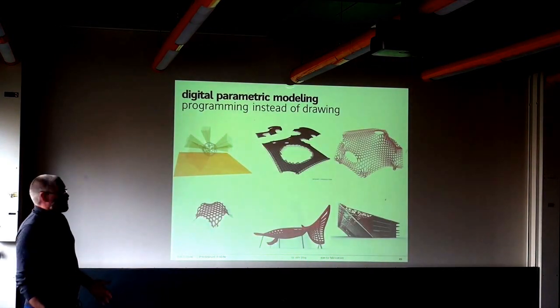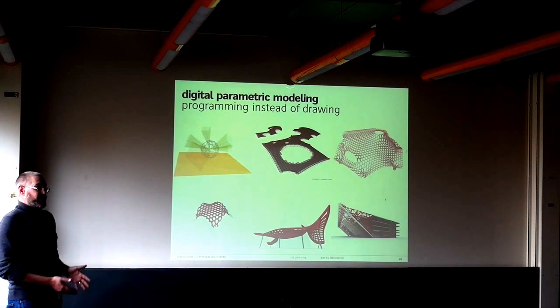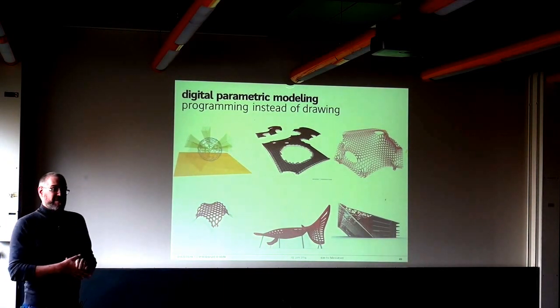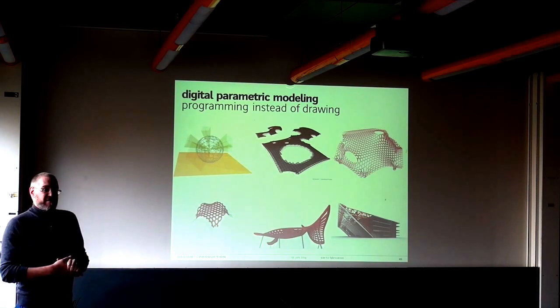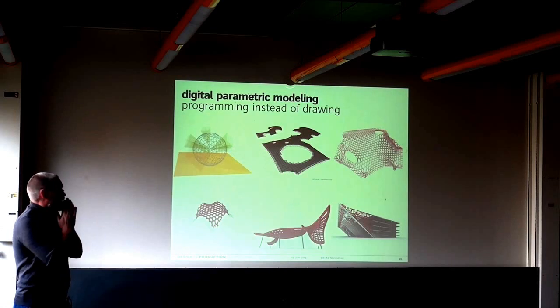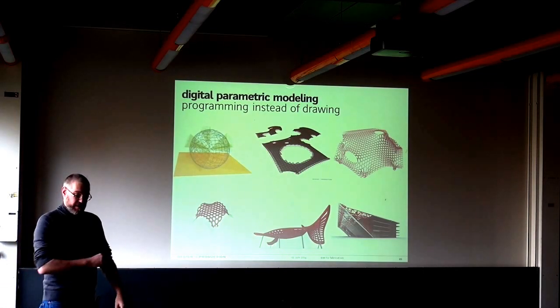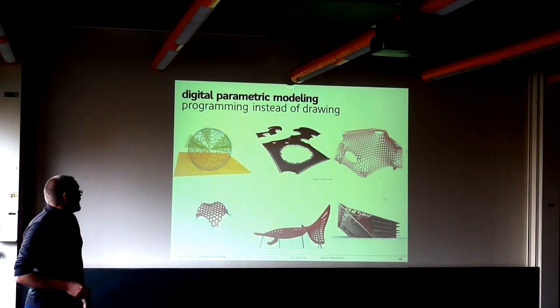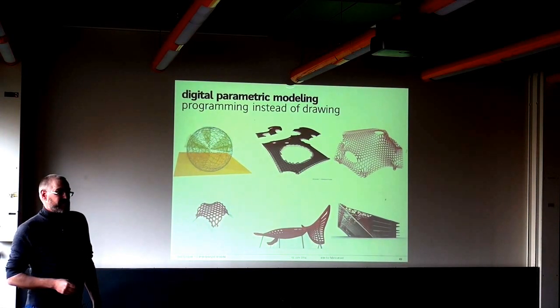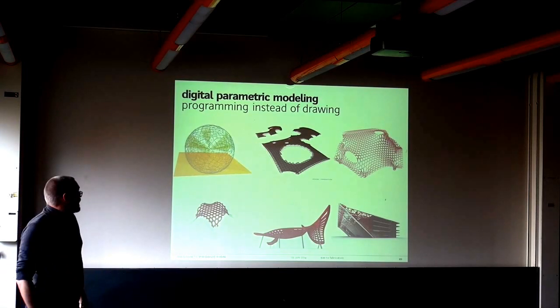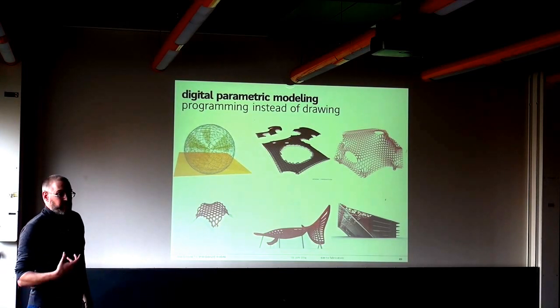So what are we doing? Of course, we're doing parametric models, and of course, we're programming those things in a rational and systematic way instead of sitting down and drawing 14,000 workshop drawings. But that means you also have to come up with very systematic detailing to be able to do that. And you have to come up with a rather stringent way to get from a design surface and the input you get from the engineer to the single component that you need in the end.